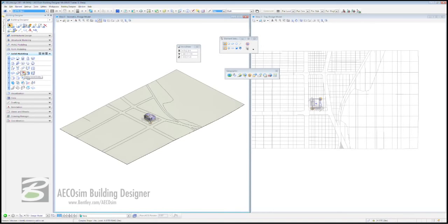We come to our Solid Modeling task again, and we come down 4 rows and to the second one in, Modify Solid Entity. In the Modify Solid Entity dialog box, choose the second icon in from the left. Also make sure distance and extrude faces are checked, and in the distance, you can enter the value of 8, to be 8 inches.